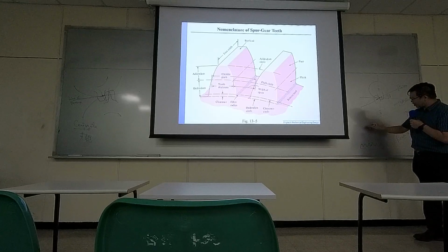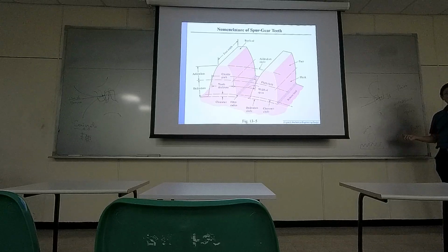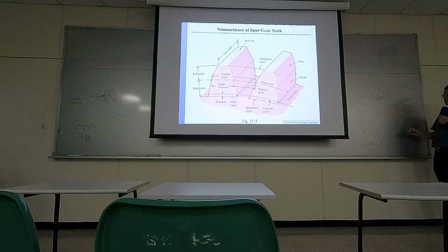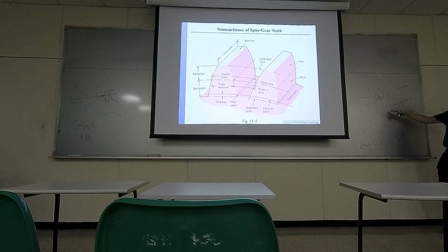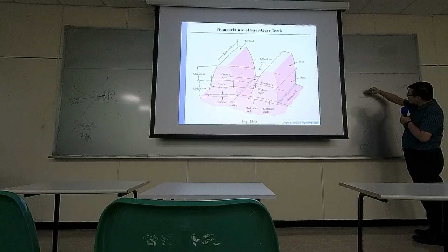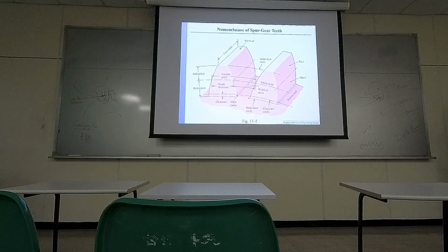Maybe there is a bearing, just like any problems that we solved in the past, and there's another bearing. And right in the middle of the shaft, you install a gear, and this gear is interacting with another pinion on the other side. Maybe here's another shaft. So two shaft systems are connected with each other by the conjugate interaction between the gear and the pinion.